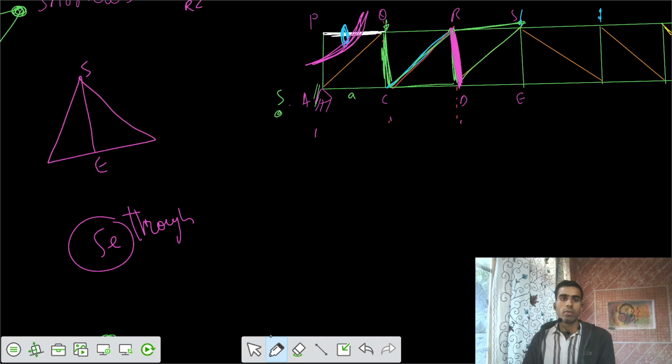We have these two triangles, and loading is applied at those joints here. And then finally, if I apply the load just at the point E, that means the reaction developed would be here. That's a positive one, because if you see the direction, this is downwards. It's tensile force developed in the member, that's away from the joint, so positive tensile.